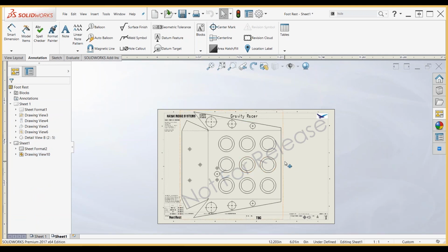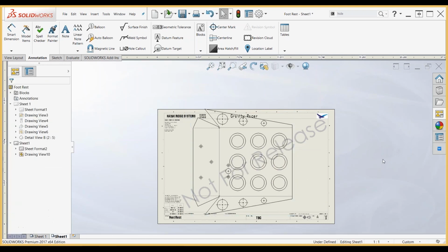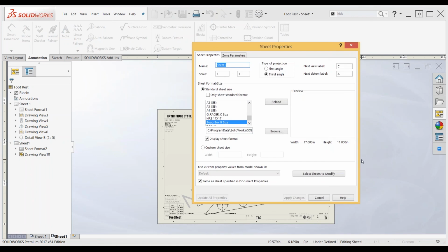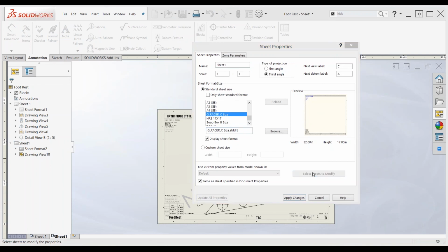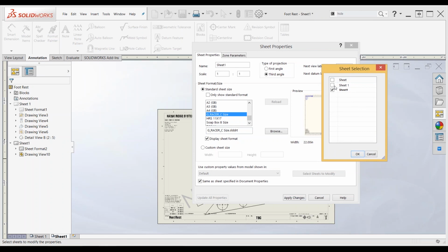So with this flat pattern here, I want to cut it. I want it to get cut out, but I want to keep the size perfect. So each cutting tool has a radius, and that radius is really small, but I need some extreme precision here for this footrest part. So what I'm going to do is I'm going to use my offset entities tool. So I'm going to grab my face, I'm going to offset my entities, but it's going to be really small.